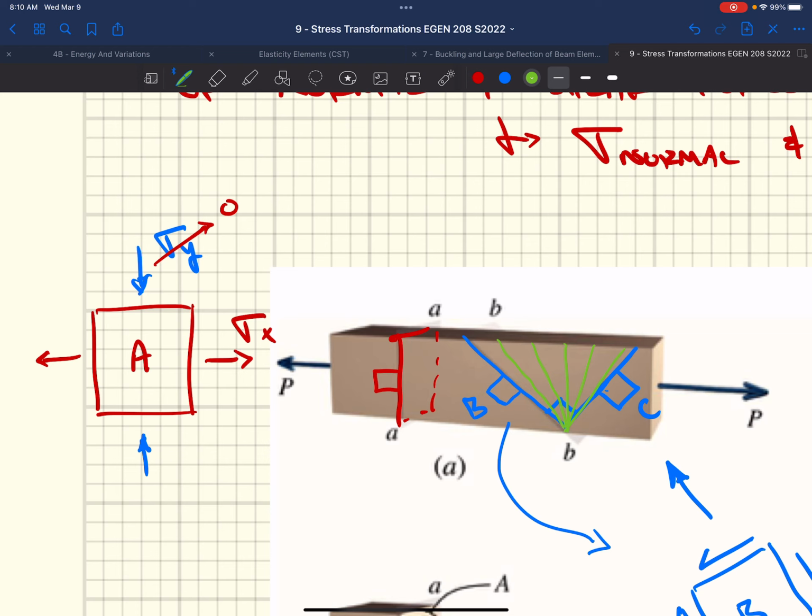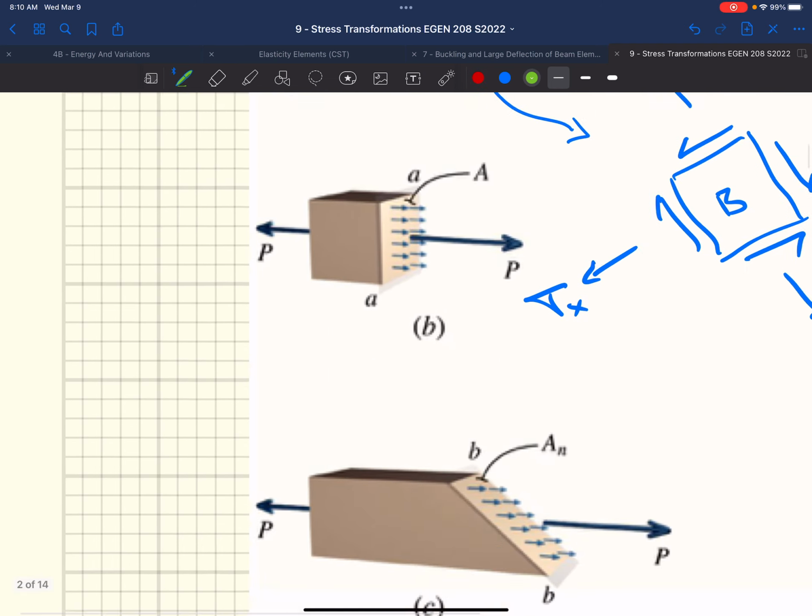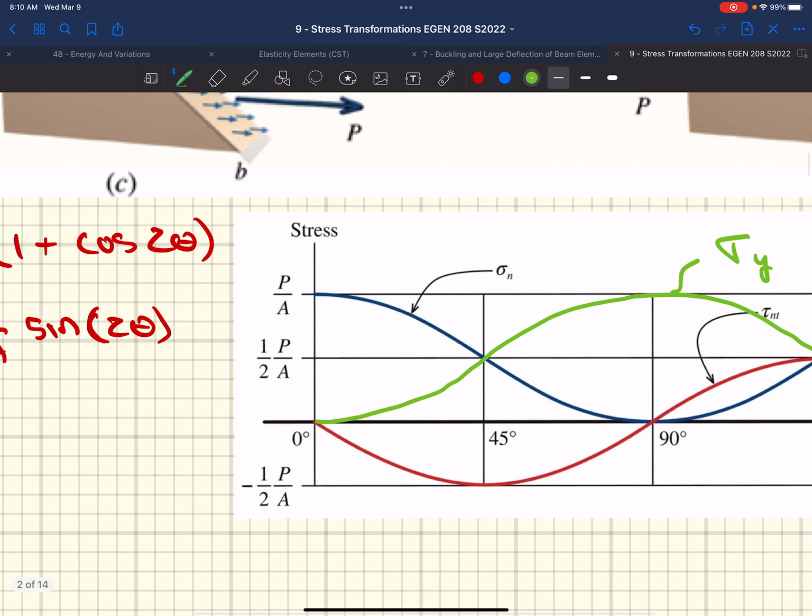And so if we just cut a plane perpendicular and said, oh, we don't have to worry about shear stresses, the normal stress is okay, we could miss the fact that there's shear stress in this material, and that material has an allowable shear stress. And that shear stress, at a given orientation, a maximum where we orient this at 45 degrees, could exceed the allowable material properties and this element could fail. So what does Mohr's circle do? Well, it allows you to see all of the stresses, not only the maximum shear stresses, but the maximum normal stresses also.